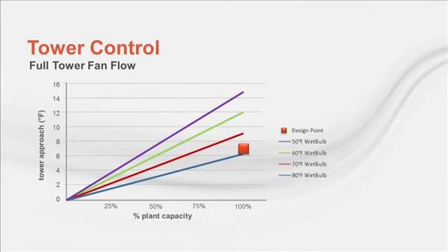You can see the tower approach linearly degrades to 0 at no heat rejection and also varies with outdoor wet bulb temperatures. As an example, if you're operating a single chiller at 80% load and the outdoor wet bulb is 50 degrees, your tower approach is 12 degrees. This would give you an entering condenser temperature equal to 62 degrees, 50 plus 12, for that hour.